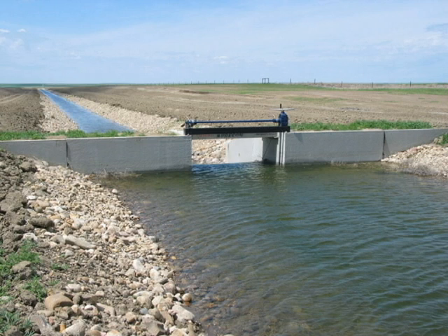Drop structures should be placed so that, if needed, they can be used to divert water onto the land. A good rule to use for the location is to place the structure about 3 or 4.6 meters, which corresponds to 10 or 15 feet, downstream from the point where the water level is 0.15 meters, which is equivalent to half a foot, above the graded land surface. This procedure appears to place the structures on fill. However, since the line represents the water level and not the ditch bottom, the structure will always be on firm ground.